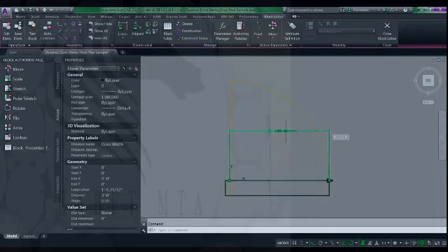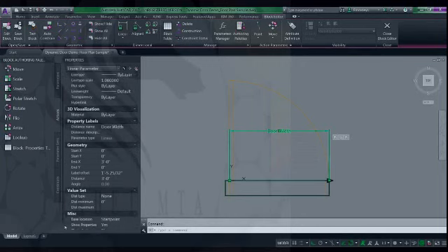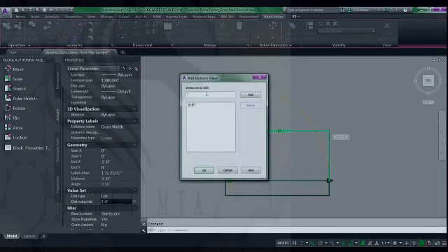You're going to select your parameter, and we are going to come to our properties dialog box. We're going to go under value set, and then within distance type, we're going to select list, and then in distance value list, we're going to select this icon right here, that ellipses. And then here you can add your preset dimensions based on your company standards, or like what I'm doing, based on how I feel right now. So I'm going to set in a couple. Let's add just one more.